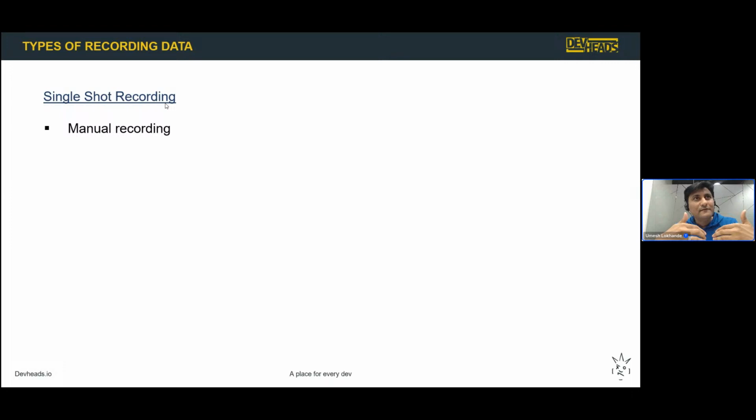manually, then we have to export from our STM32 Cube IDE, say for example, in this case, because I'm using Cube IDE for debugging. So from the memory view of the IDE, I have to export it to another software application. That's SystemView, right? So it's a very manual process. I will show you both processes live.